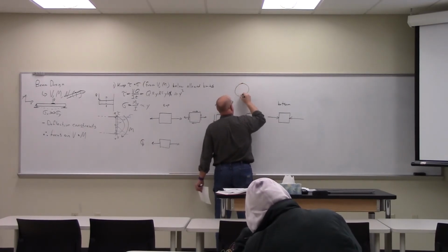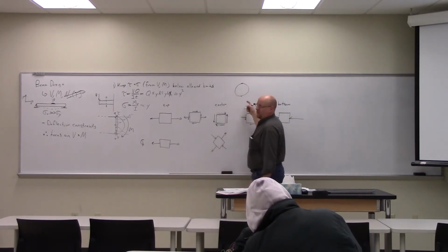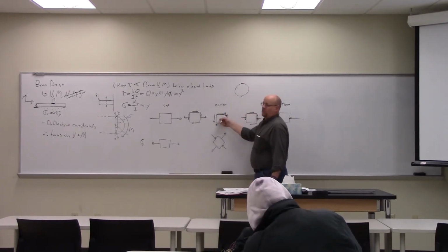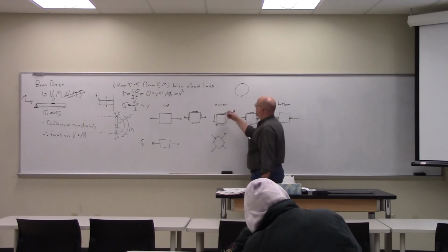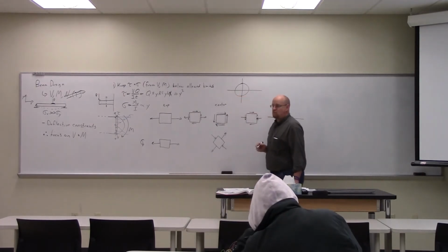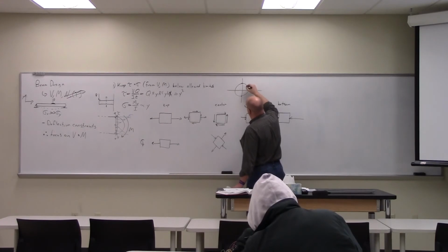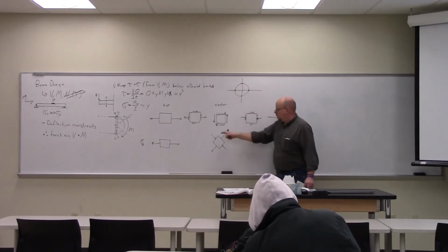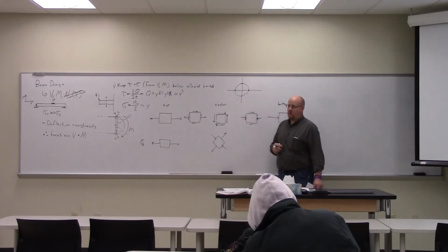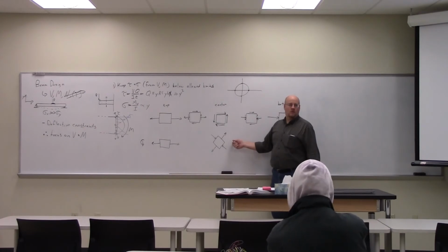I'm sitting at this point and this point, right? What is my sigma value at this point? 0. So my axes are like that. When I rotate around 45 degrees, one is at a negative value, one at a positive value. One is compressive, one is tensile. Everybody see that?